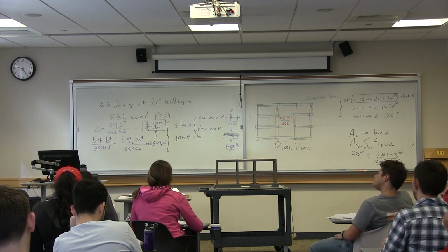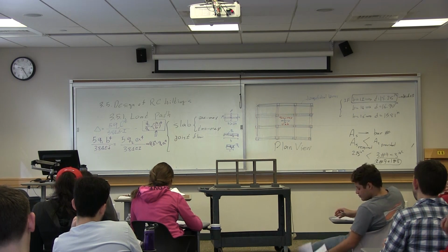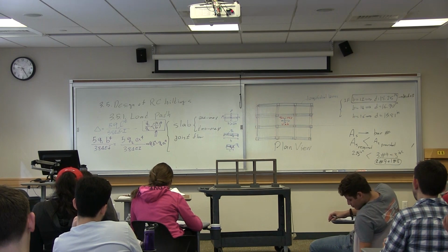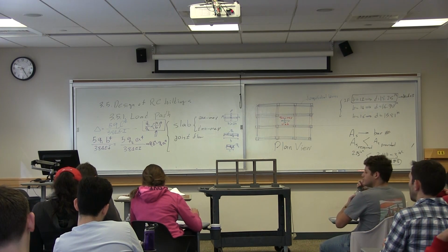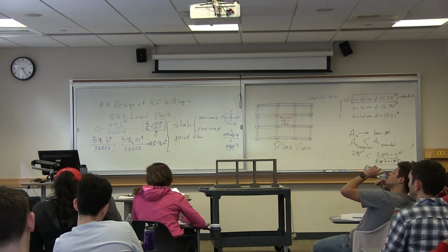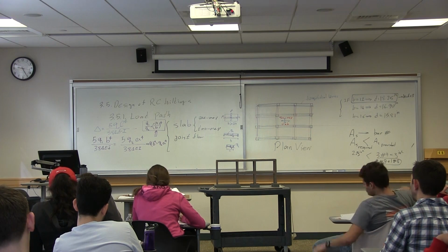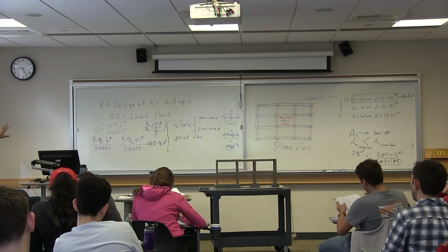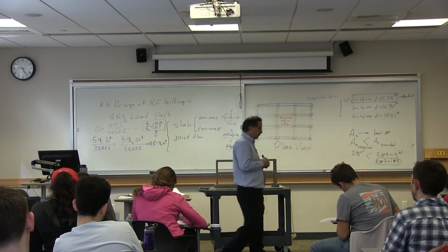One could say, let's say we don't know this, say half of the load goes in the shorter direction, half goes in the longer direction. That would be very wrong, right? Because 16 times goes in the shorter direction, 1 time goes in the longer direction. So understanding the load path and the floor system is crucially important.